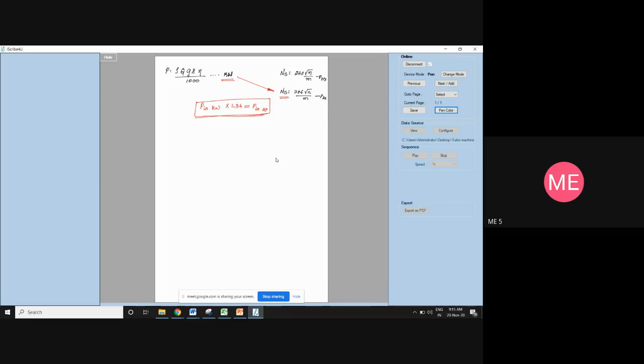Anybody got the answer? So we got the P. What is the Q formula in this? Q is equal to N into pi by 4 into D square into V1, and V1 is Cv root of 2gH. That we know. And the standard Ns formula, which is important, Ns is equal to N root P by H to the power of 5 by 4. This is an important step.